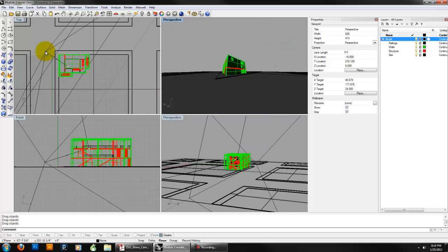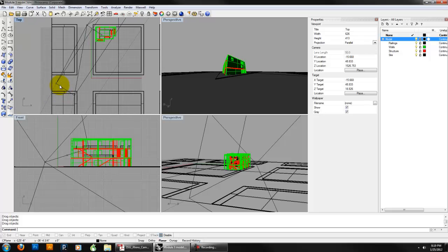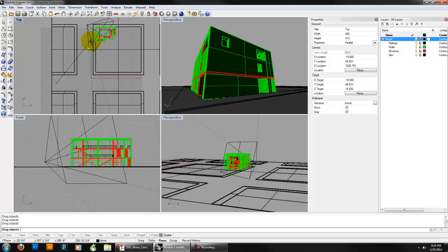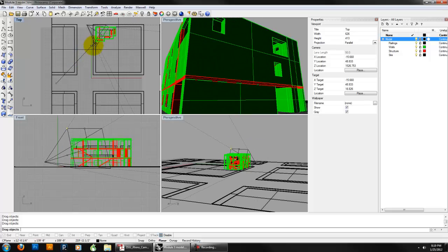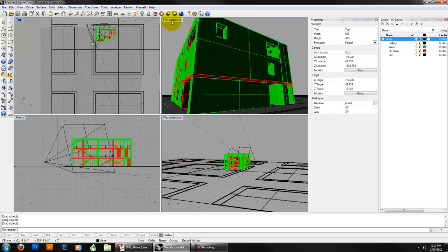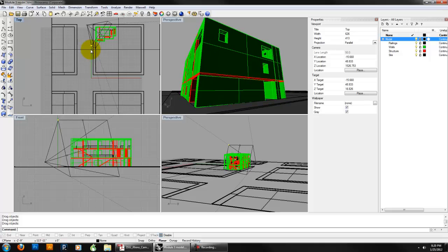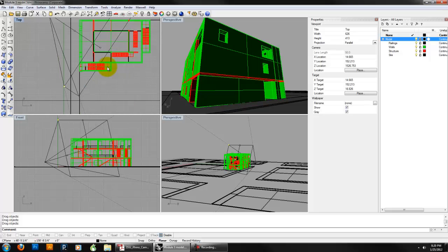And so if you change that perspective, zoom out here, look at that, and you can change that visually by playing with this focus point. You can see if I move that cone of vision, I can actually interact with it. You don't see it update here, but if I go back to my perspective, you can see that that's changed. So this point actually stretches that box, and that's going to say what's in the view. Look at, this is your measuring plane, and this is what's out on it. And you can see that we actually catch some of the sidewalk here and some of the sidewalk there. And so that is actually what we're seeing in this viewport.